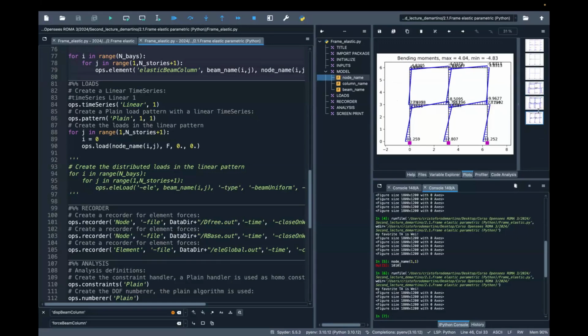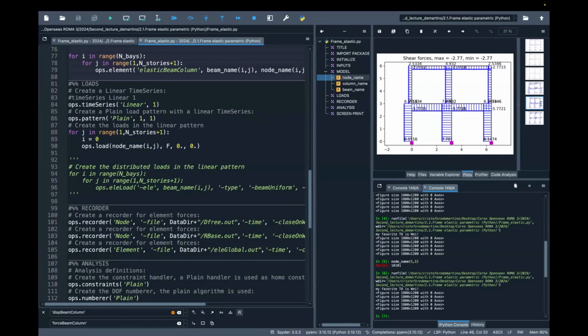bending moment diagram. So this is a general check, guys. I'm generally asking, especially students when they start to build a frame, remember that there is a very simple check you should make on a frame, right? The total shear force at the base should be equal to the total lateral force you're applying, okay? In this case, if you keep in mind we are applying two forces of 10, right? Obviously, we should get that the sum of the shear should be equal to 20, right? Okay, this is a very basic check you must always do on your frame.